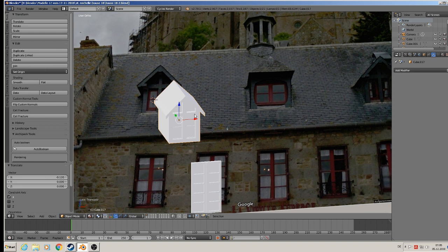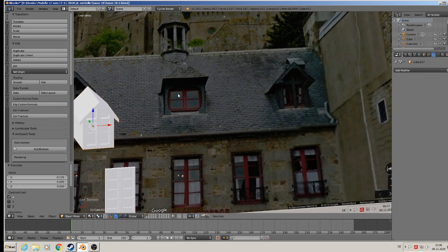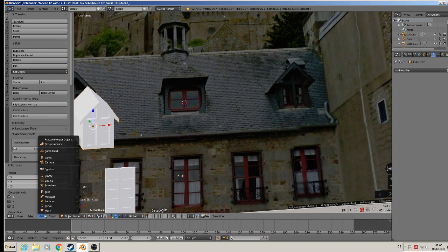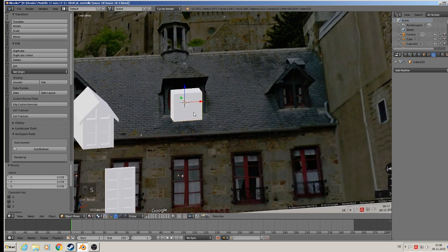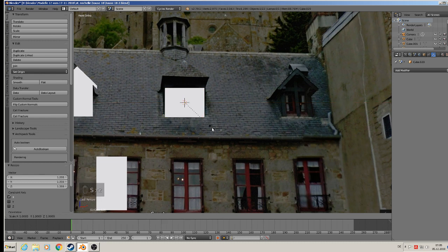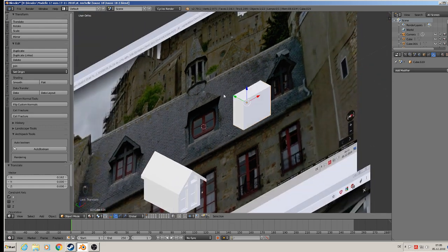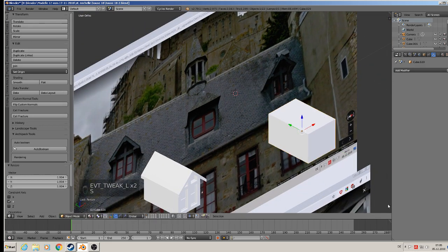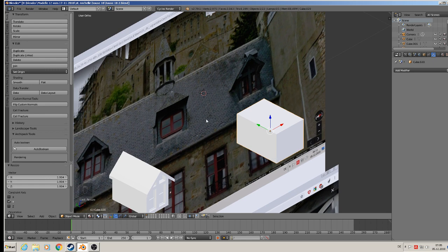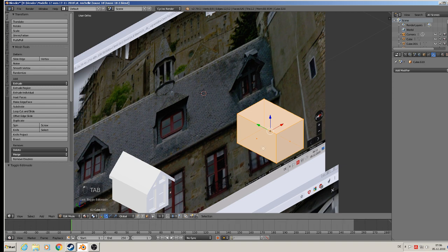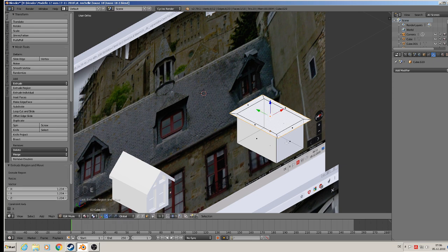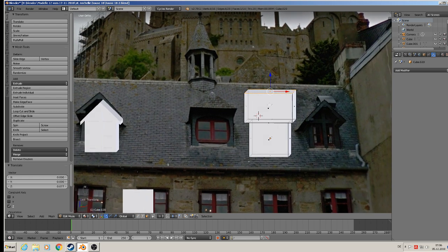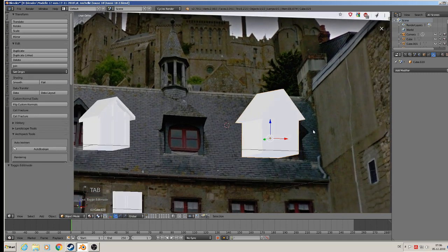And then we make the other part there. So we see what we can do. Here we need that, okay. So add mesh, cube, scale down, scale X, scale set, done. Then scale Y, it must be longer because the roof has a lean and that must go through the lean. So we need that rooftop styling there, so we take the top face here, extrude, scale, and have that, then extrude to the top, and then scale X again. So we have that overlapping look there.